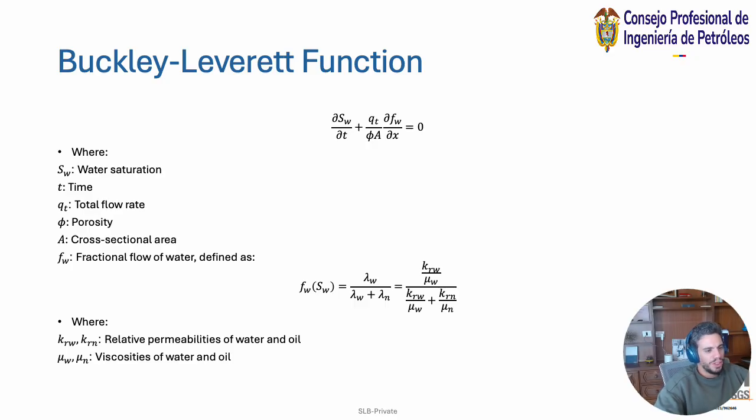So the Buckley-Leverett function is again one of the most important equations in reservoir engineering, and this theory predicts how one fluid is able to displace another. So if we're looking at water displacing oil in a given porous medium, it's used a lot when you're looking at reservoir engineering approaches, such as water flooding or enhanced oil recovery.